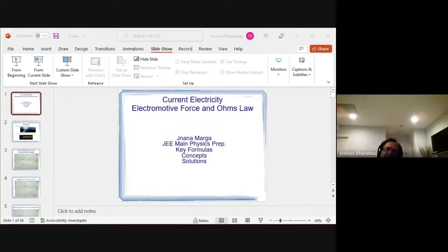If you connect them correctly, you'll have 1.5 plus 1.5 in series. You can also connect them in parallel. So what is the aim of all this? By connecting them in series, you increase the voltage. If you want to keep the voltage the same, you connect them in parallel.